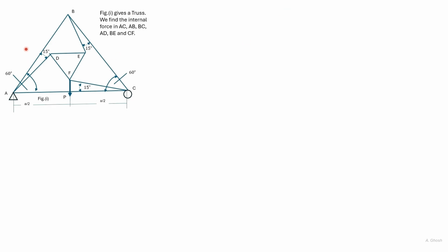Consider a section here. Then resolving forces in the vertical direction will get a relation between the force in AB and AD. And resolving the forces in the horizontal direction will get the force in AB and AD in terms of the force in AC.